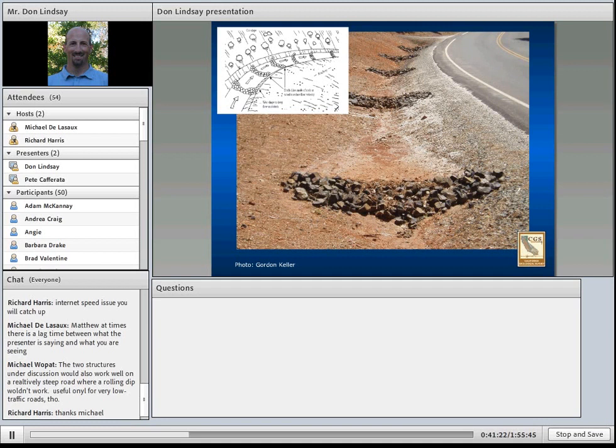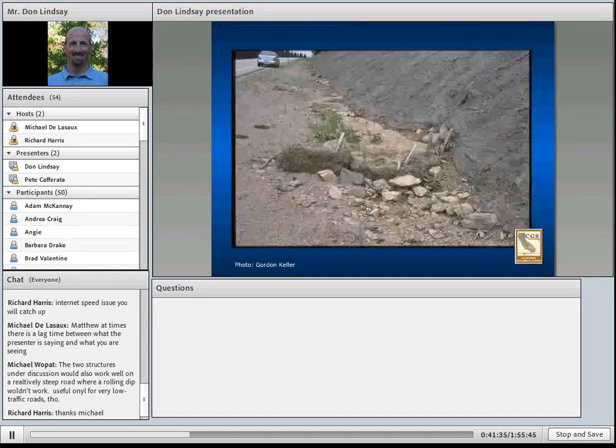Check dams require extensive maintenance to remove the settled sediment. If this is not performed, the trapped sediment can be resuspended during subsequent storms or when the check dams are removed. Here's an example of a check dam constructed out of staked straw bales.